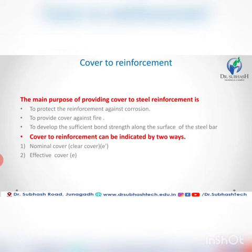First, nominal cover or clear cover. The thickness of concrete from the surface of reinforcement bar to the nearest edge of concrete is called nominal cover. Second, effective cover. The thickness of concrete from the center of bar to the nearest edge of concrete is called effective cover.